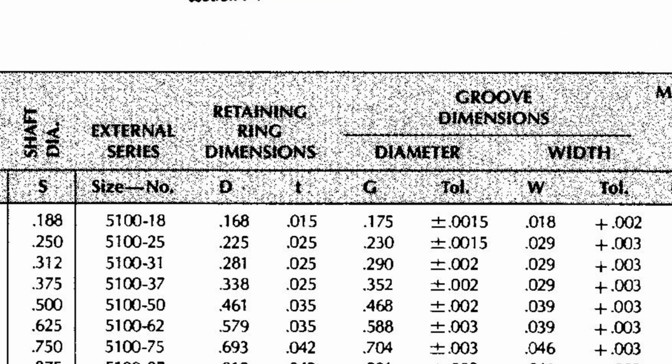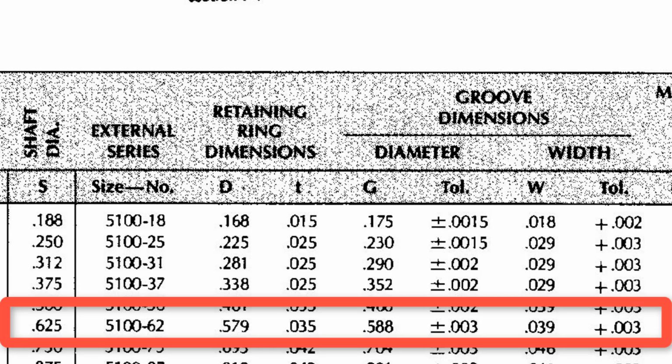In our modeling, our diameter is 0.625 inches, and the groove diameter is 0.588 with plus minus tolerance 0.03, and the width is 0.039 with plus 0.003 inches.